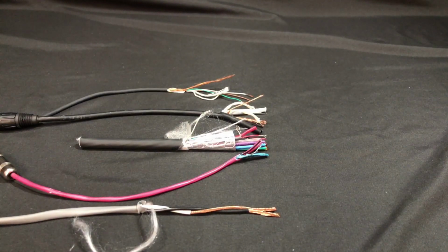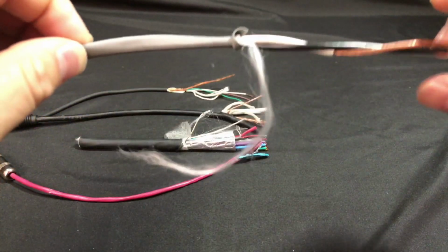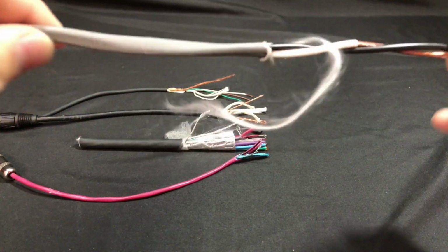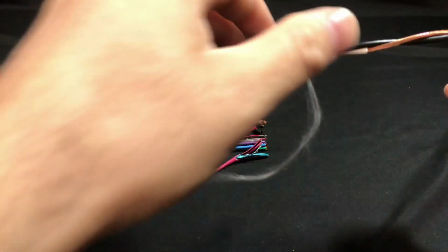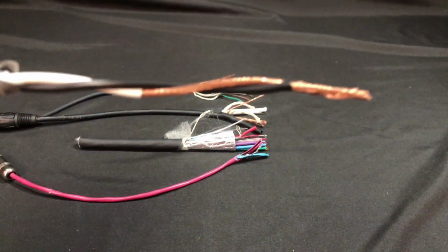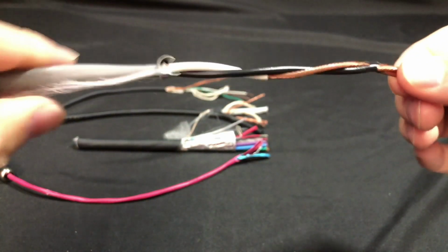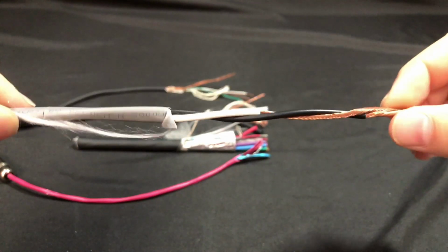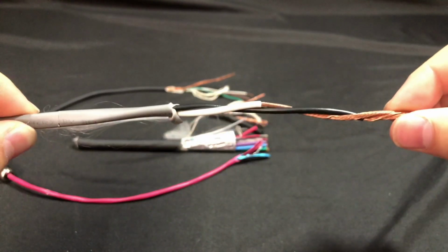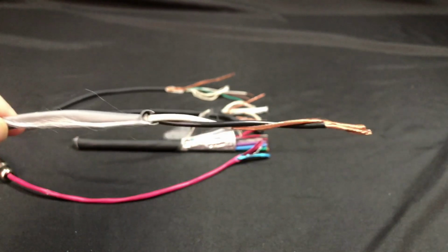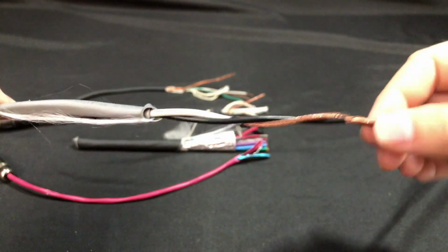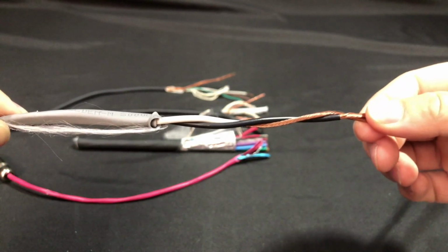Okay, now I'm going over the 3 different types of cable shielding as seen on page 38 and 39 of the book. The first type of shielding is called a serve, and that's simply when 2 conductors are wound helically around each other. This doesn't actually help against any radio frequency or electromagnetic interference. It's simply a way to reduce capacitance between the 2 conductors, which will help against RC low-pass filters and, for high impedance signals, against the cable turning into an antenna.